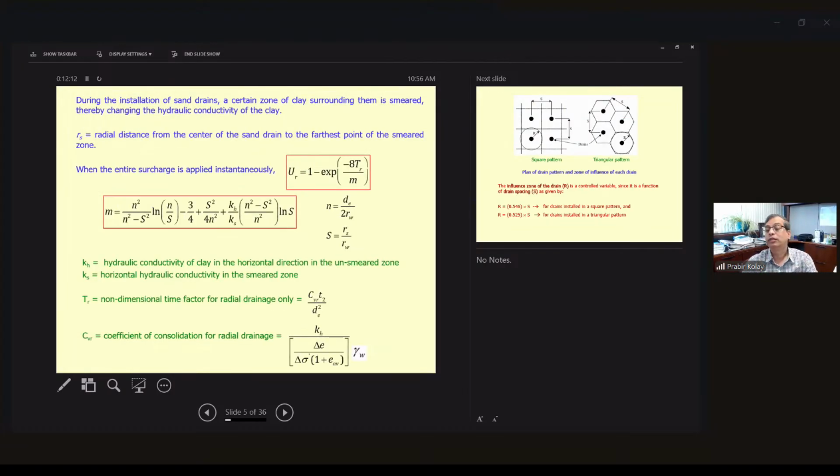So there are a few equations in the consolidation equations when the flow is in the radial direction. While talking about consolidation, the degree of consolidation U is in the vertical direction. Generally you don't write that, because the exact theory is one-dimensional consolidation in the vertical direction.